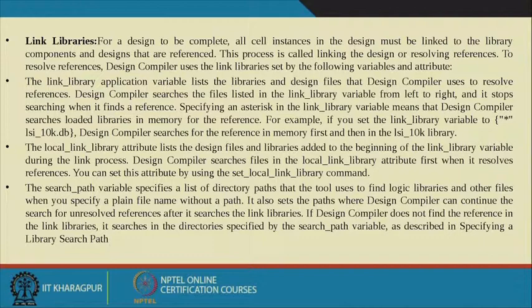So, link library I have already said, and then another variable which we can put is search_path. The search_path variable specifies a list of directory paths that the tool uses to find logic library and other files when you specify a plain file name without a path.